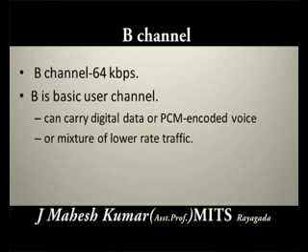B channel is basically adapted for telephone digital networks with common channel signaling. Digital telephone networks have evolved around A-law and mu-law encoding of speech signals at 64 kilobits per second. ISDN has the same rate for the basic information channel, although the technology has advanced to a stage where quality voice can be transmitted at 32 kilobits per second or even less. Having adopted a 64 kilobits per second rate, ISDN, however, permits low rate signals to be transmitted by using rate adaptation. Alternatively, a number of low rate information channels may be multiplexed and sent on the B channel.